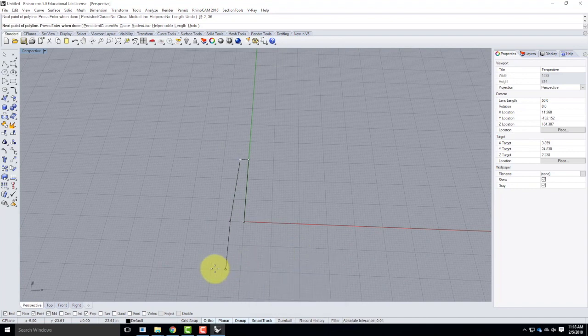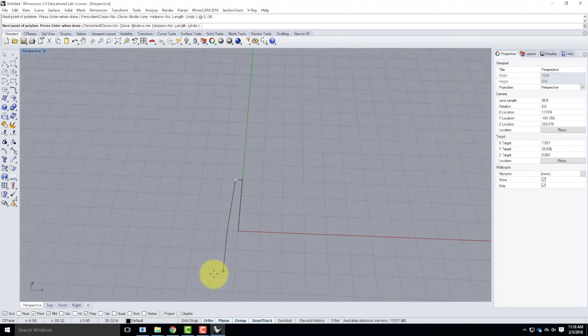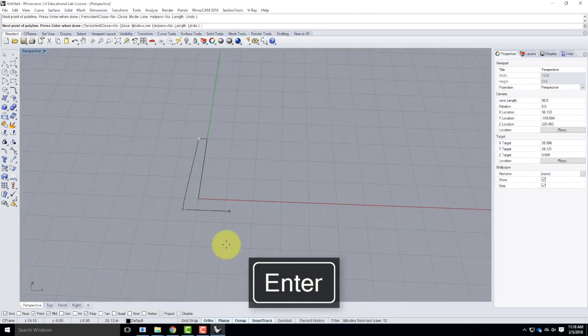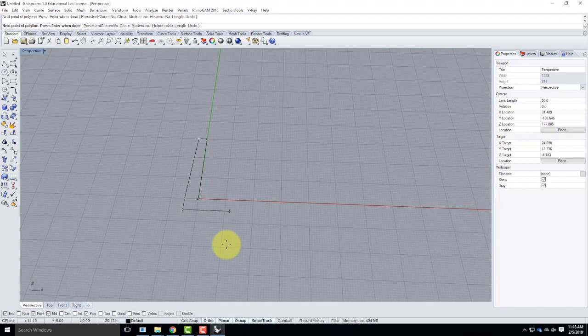So you guys see, obviously, that I gave you this because it's a little complicated. So I'm pushing you a little bit. That's the point. So I'll continue by going down 6 inches. So I'll type 6, enter, and a direction is going down. So I click. Next one is going to go over 30 inches and down 6. So again, I'm going to use those relative coordinates, and it'll be at 30, comma, -6.